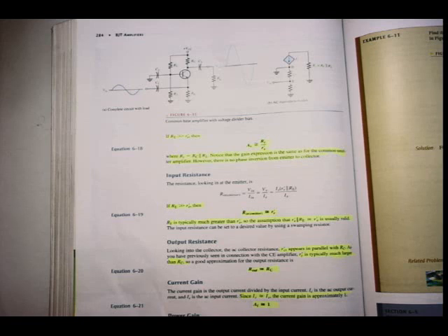So thus the same then as for the common collector amplifier, where the voltage gain was equal to the current gain, because the voltage gain was approximately 1. In this case, the power gain will be equal to or equivalent to the voltage gain, seeing that the current gain is approximately 1. Alright, so those are the parameters for the common base amplifier.